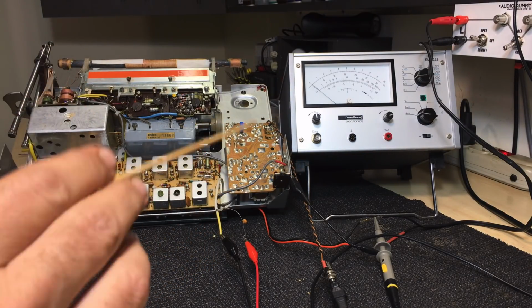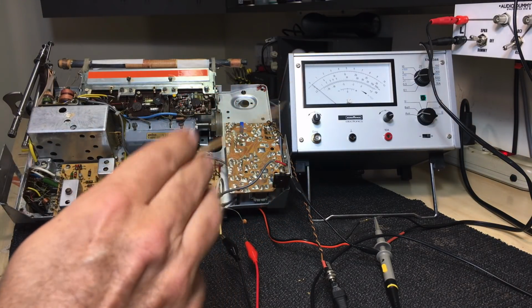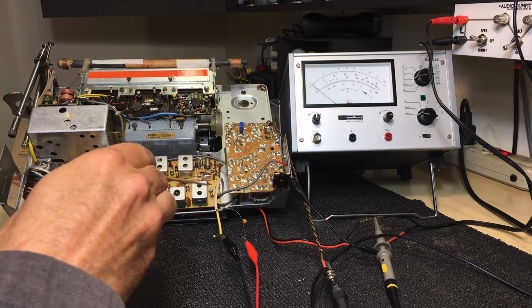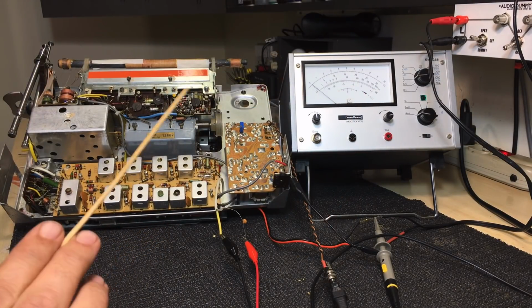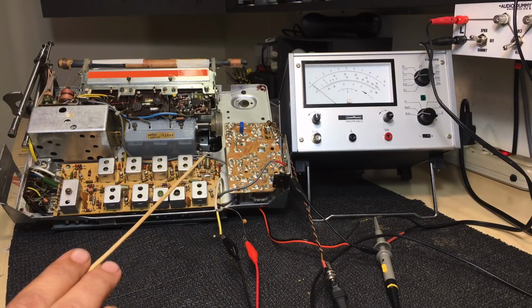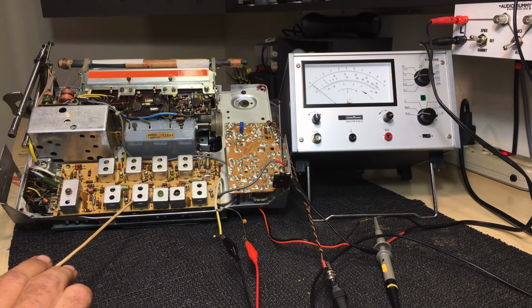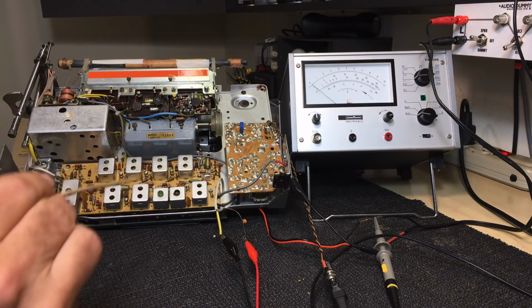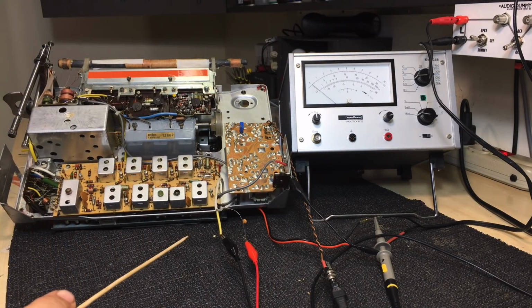And if you're sending in, say, a 600 hertz tone, the level of that tone will tell you just how well aligned these IFs are, because it means it's getting through optimally, okay? The AGC voltage method is a bit difficult here because it's got a pretty big capacitor in there, and that means that because the capacitor takes time to charge and discharge, it actually slows down the response. So it's not absolutely responsive.